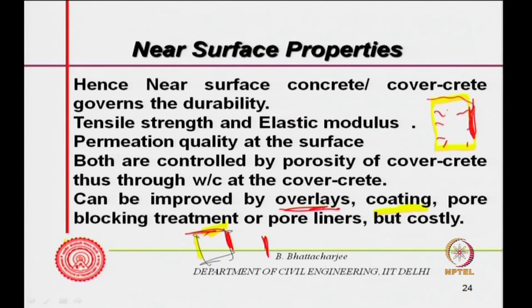Some of them react with the substrate to block the pore. Some might act at the boundary of the capillary, react or get adsorbed there, and in the process they change the contact angle of water inside. Since most of the ingress is through water, it will not allow water to come in.